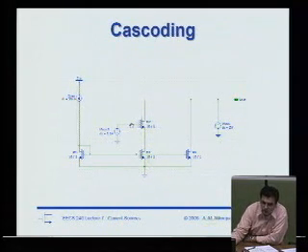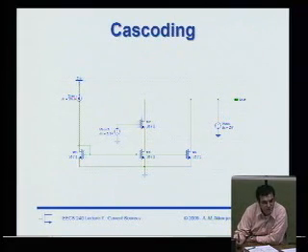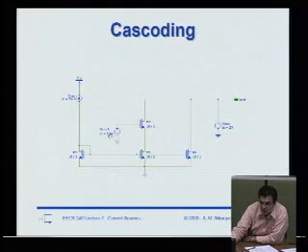So I really shouldn't bias this more than, let's say, 2 overdrive plus 1 VT, not 2 VT. But we'll do that calculation more carefully in a moment. For the moment, for this simulation, it's just at a fixed value.